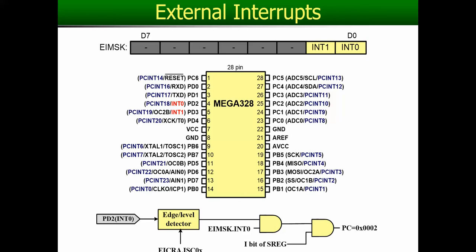For example, a certain signal goes high and it stays high for 10 milliseconds, or maybe 100 milliseconds, or it stays on forever. In case of a high, we don't want to be interrupted 10 times in 10 milliseconds, we want to be interrupted once. We have to decide whether we are waiting for the edge to occur and then we'll interrupt the CPU, or a level. So that detector.